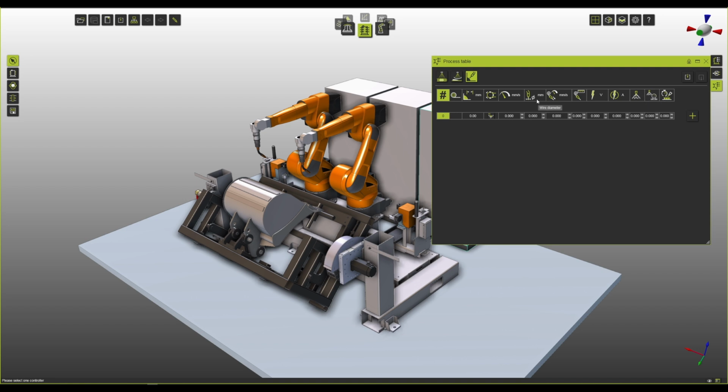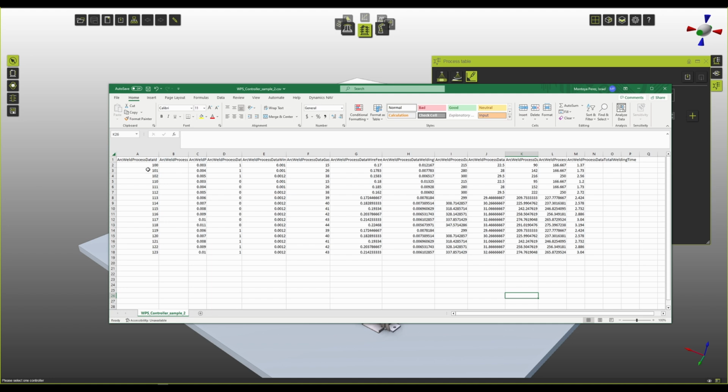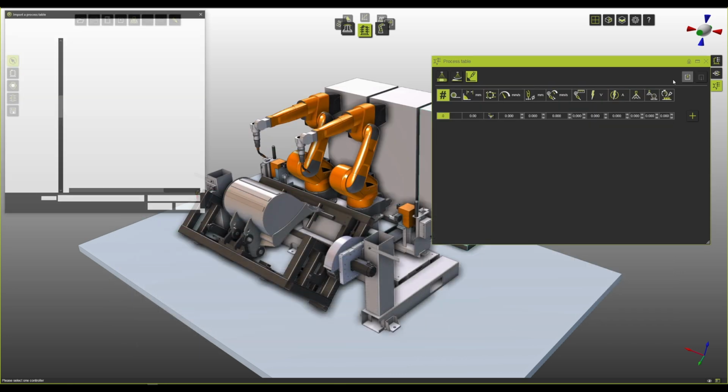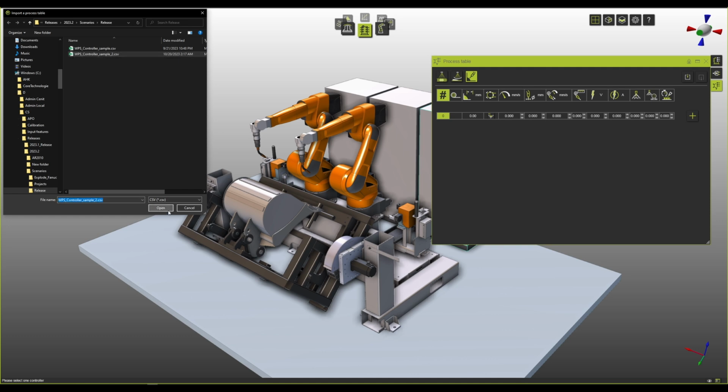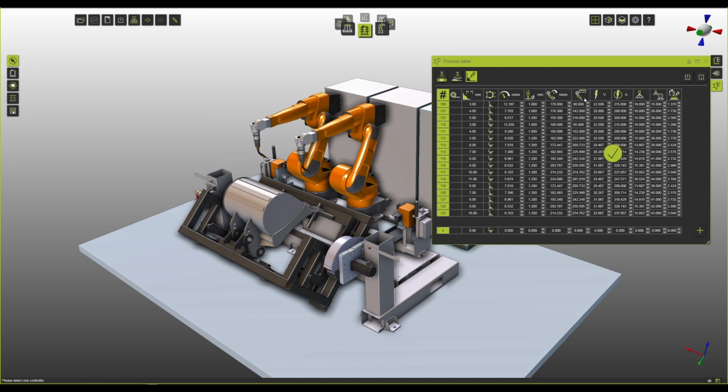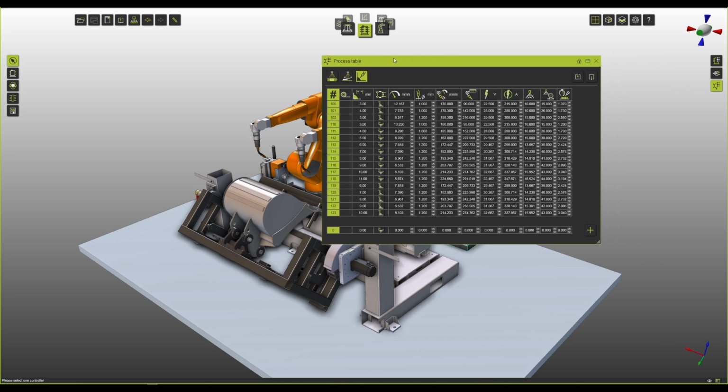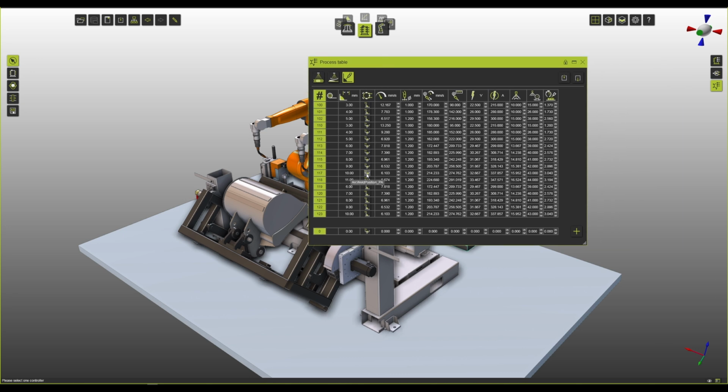We can of course customize how many things are shown here and how many of these we are going to use in our final program. But the idea is that you gather a database, the same database that you are creating for your programming schedules, to be translated into the software. We don't want you to do this manually. The idea is that you create a CSV table, and then you import it directly into the software with whatever hundreds of types of welds that you have proven and tested, and you know they work with the right settings that you have gathered with your welding expertise.